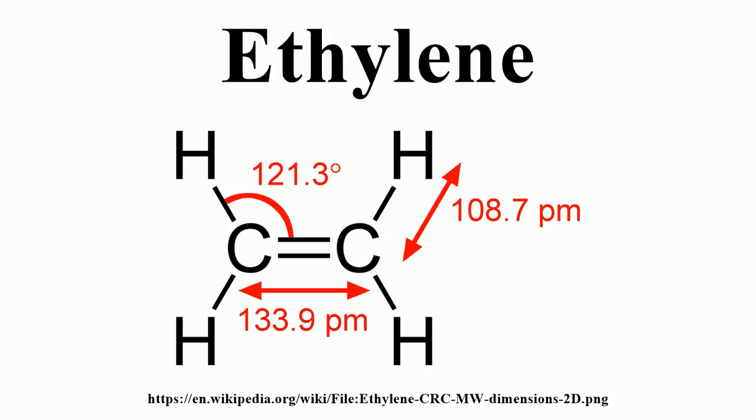The C2 stream contains acetylene, which is explosive above 200 kilopascals. If the partial pressure of acetylene is expected to exceed these values, the C2 stream is partially hydrogenated. The C2s then proceed to a C2 splitter. The product ethylene is taken from the overhead of the tower and the ethane coming from the bottom of the splitter is recycled to the furnaces to be cracked again.